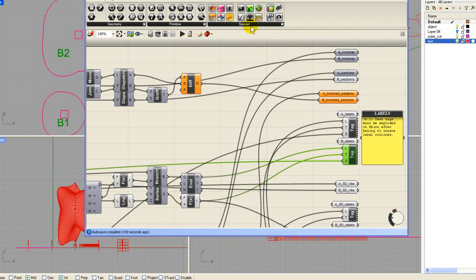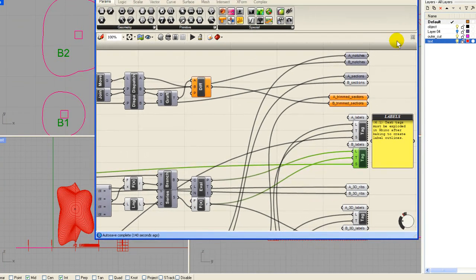Okay. And while it's selected, we want to come back in here. We want to make that the active layer in Grasshopper. And we want to come over here to our Bake element node and bake that in. Okay. It'll take a second, and we'll come over here, turn off our preview.